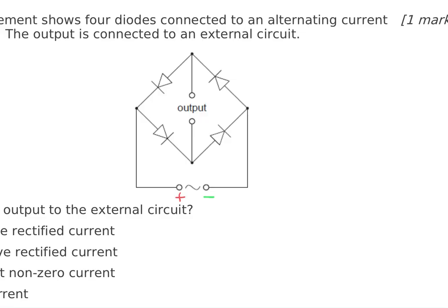So it really doesn't matter which side you make positive, which side you make negative. Let's trace. Alright, so positive terminal goes around. It stops because the direction of the diodes is for positive flow, so it's going to stop there. It's going to go through this guy and to this terminal of the output voltage. Yippee. Now let's trace negative. So it comes around here, comes around here, and then it stops right here, and it goes through there. No, it doesn't.